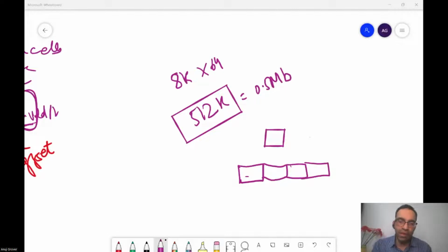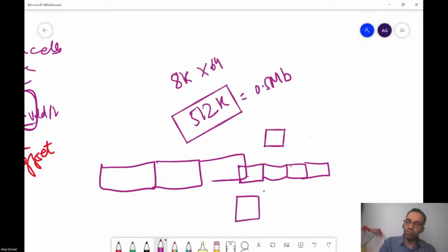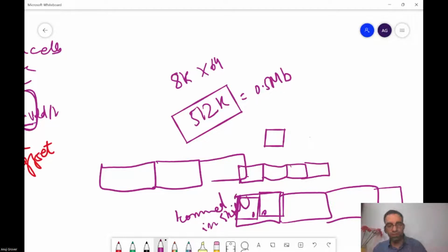So in SKILL, you can actually write programs so that you can tile cells next to each other and make arrays. So you just make one IO, you flip it, and then this one block you can repeat as many times as needed, let us say so that you have 10 IOs or 22 IOs or 32 IOs and so on. And this can be done simply by one command in SKILL. So it's a good opportunity to learn SKILL.